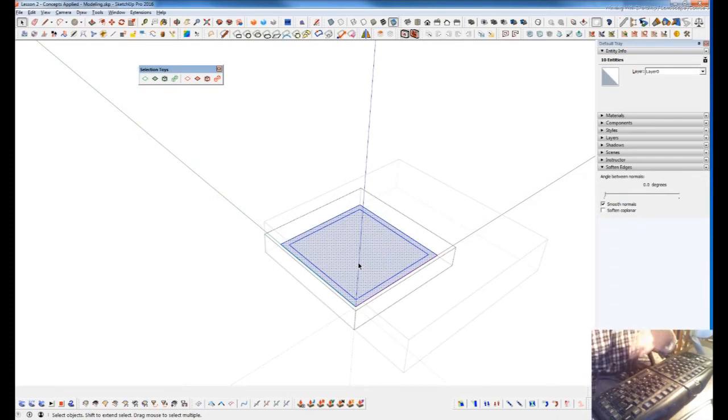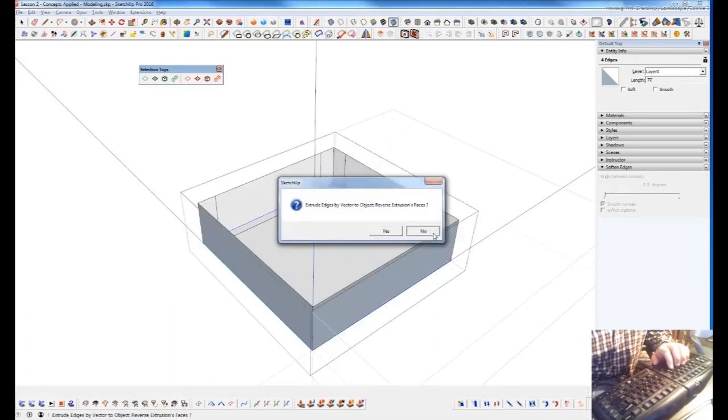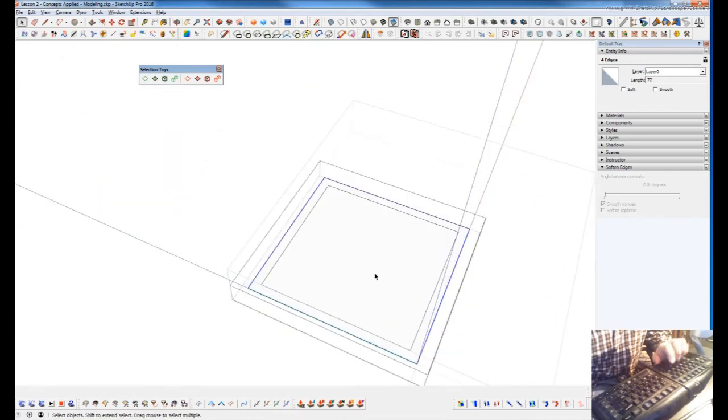But obviously something that was very busy, even a terrain that had hundreds and hundreds of faces where you just wanted to select the outside, I have that set up to Control B. So I can very quickly select the border edges, and from there I could even use our edge extrusion tools and things that we talked about with extruding by vector. We could grab those and manipulate those edges because we very quickly got to the border edges that we wanted.